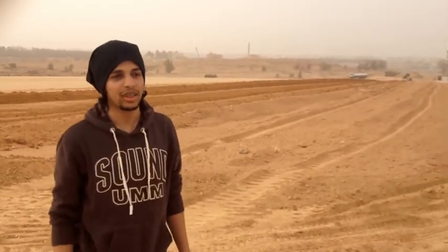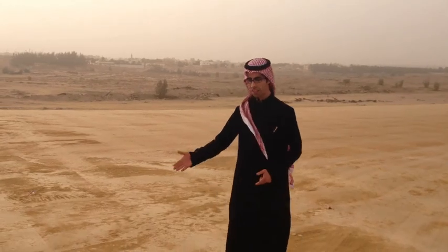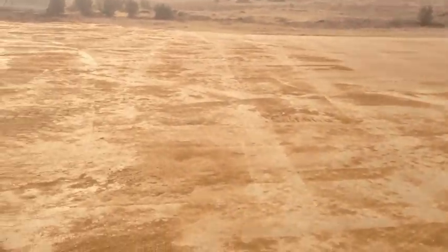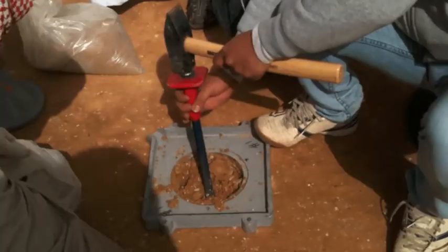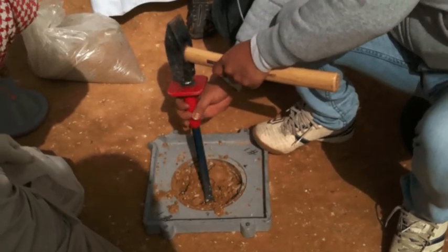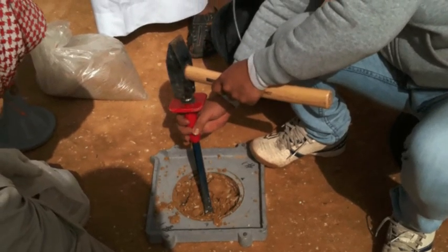Rosan Company put in a layer embankment in order to raise the road and upgrade the path for the bridge. The layer embankment consists of a mixture of materials, small gravel and sand. The specification states the thickness of each layer must not be more than 30 cm. There are many types of soil compaction tests performed on soil. Some of these include the sand cone method, one of the most common tests to determine the fill density of soil.